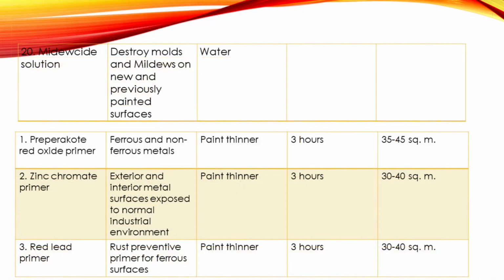So a primer or undercoat is a preparatory coating put on materials before painting. Priming ensures better adhesion of paint to the surface, increases paint durability, and provides additional protection for the material being painted. One example of a primer is the zinc chromate primer.